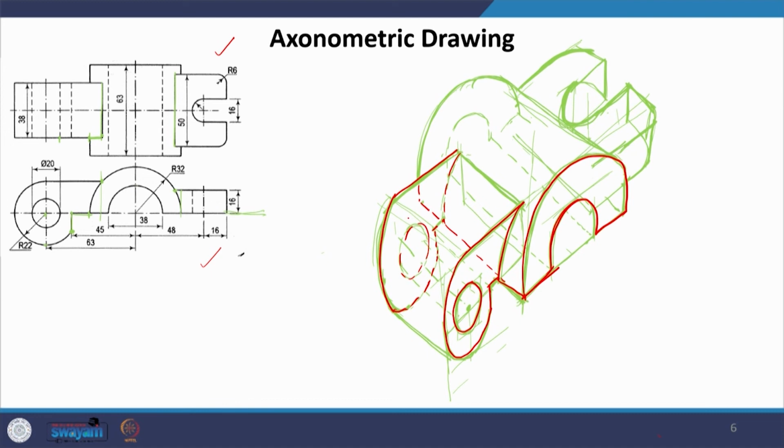This is what you will see in the front. In the back, we have this, the tangent coming, joining this. There is a hidden part going behind. Now, here we have a tangent joining the semicircular part, a straight line. That is approximately how this object will look, and you can very clearly see that we have been able to draw it simply starting from the plan and just taking the heights.